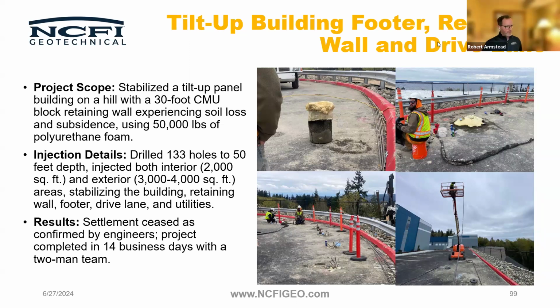I actually really like this question a lot. If a deep injection behaves in a heterogeneous way, looking a little like an anthill almost, then can a grout curtain really be watertight? Does a grout curtain require a secondary grouting with a single component grout if you want it to be truly watertight? It certainly can't hurt.